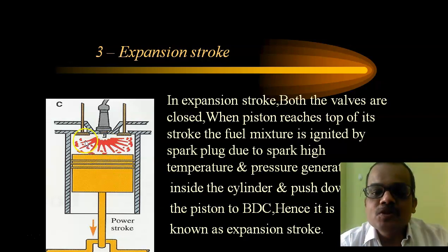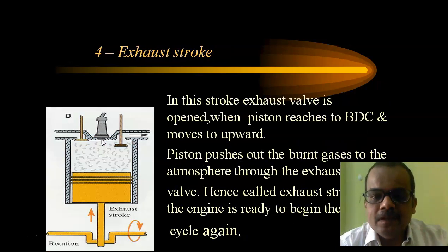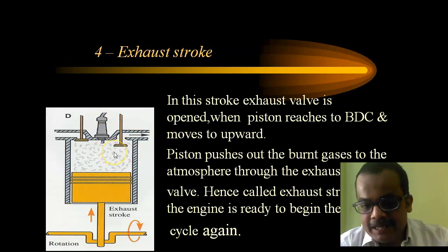And in this also, both the valves are closed. And last stroke, in an exhaust stroke, again the piston will move from the bottom dead center to the top dead center, BDC to the TDC. So now, after the power stroke, this cylinder is filled with all the exhaust product, exhaust gases.